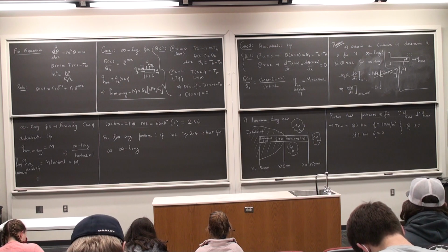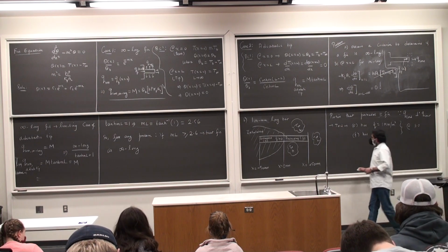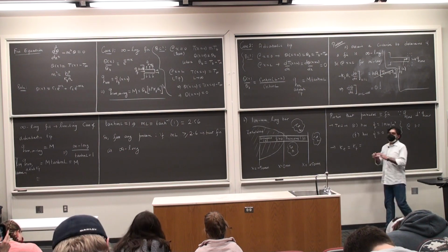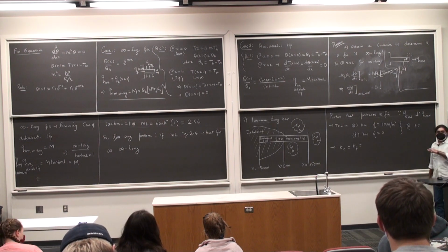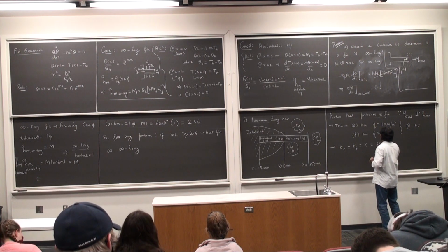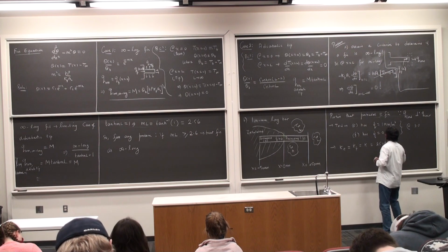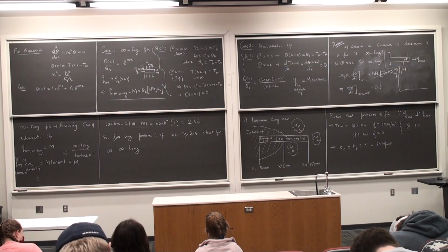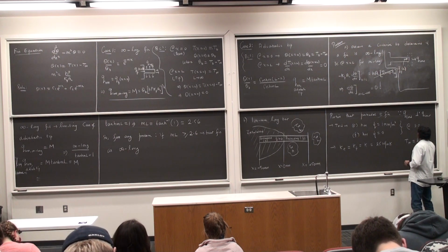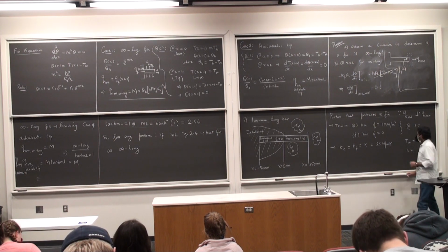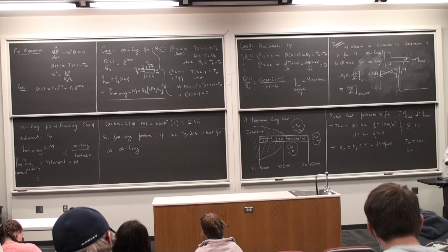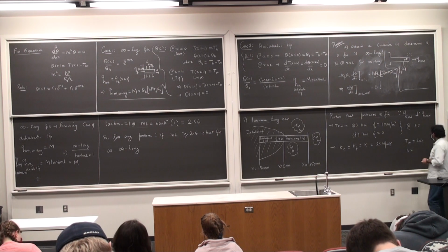Okay. And I'm told the other information, thermal conductivity, K embedded is the same as K fin because this is the same body, right? The same thing that is protruding out. This is equal to some K, which is 25 watts per meter Kelvin. Okay, this is one. Then T infinity and H is given to us. 20 degrees, and H, I believe, is 100.